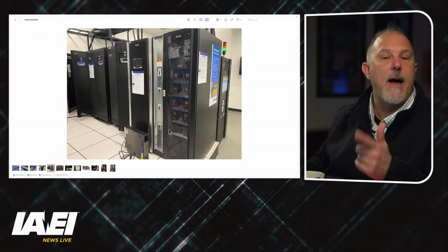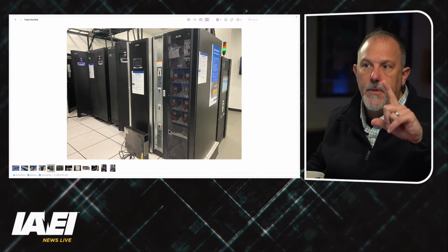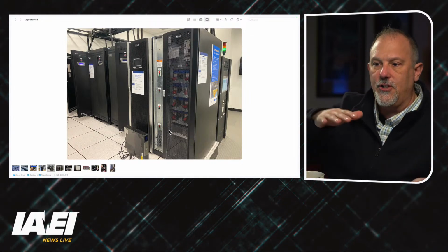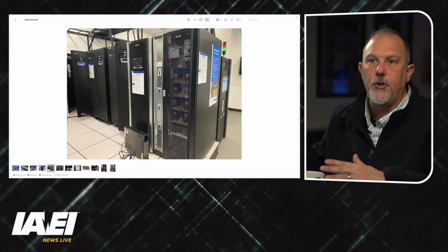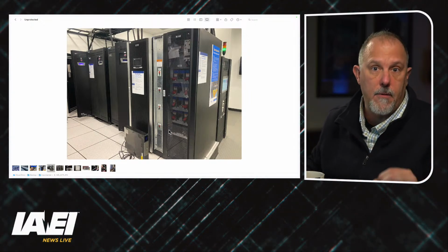I'm not going to run off of a super cap for hours. I'm going to use that as a ride through, and that's why you'll see them in data center applications where you need power for that short time transition when you're going from one source maybe to another. We have to have zero interruption.